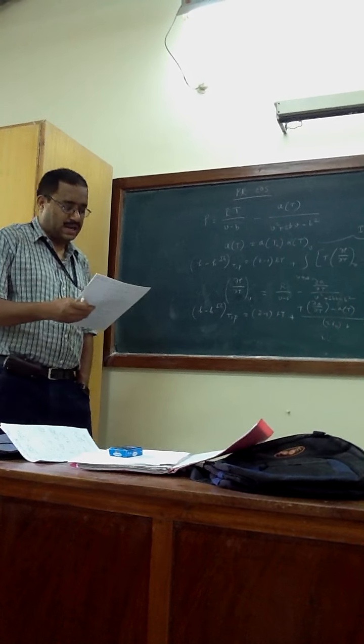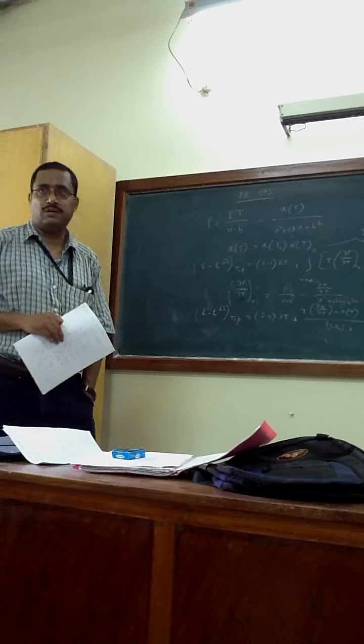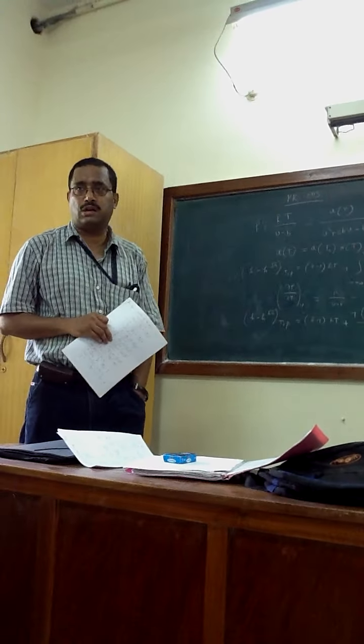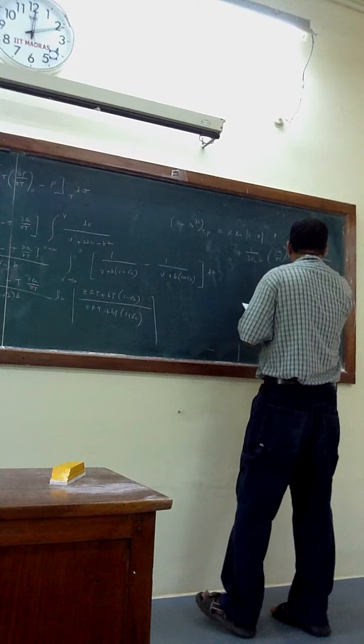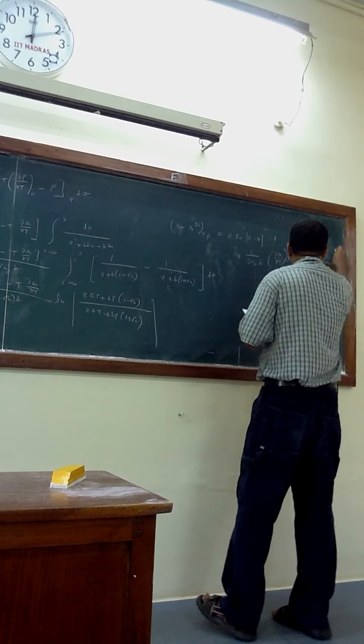So similarly, one can get S minus S^IG at T, P. Okay, did you get the answer? S minus S^IG at T, P equals R ln|Z minus B| plus 1 by 2 root 2 B dou A by dou T ln|Z plus B into 1 plus root 2 divided by Z plus B into 1 minus root 2|.